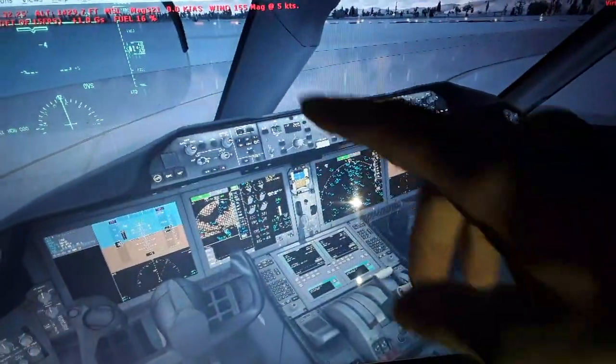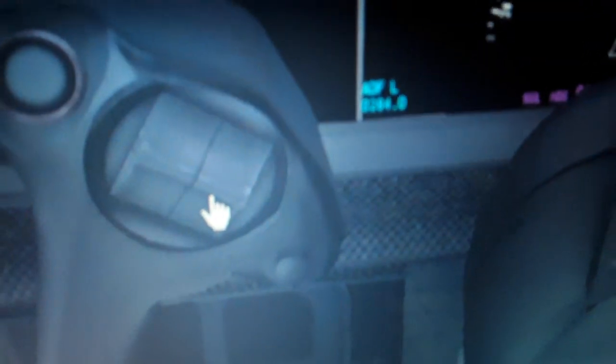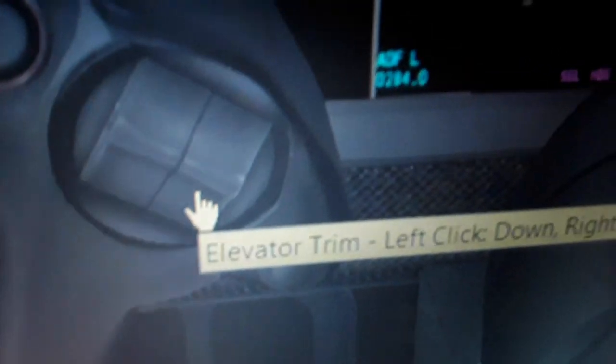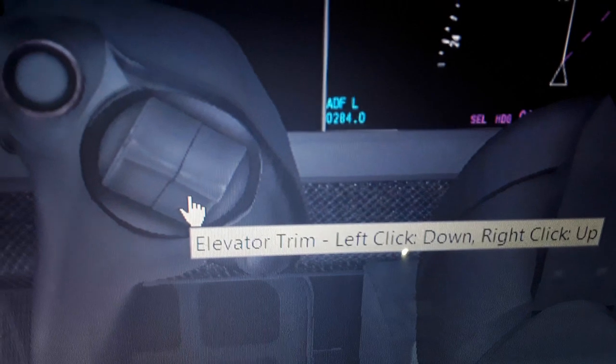So after you disconnect the horizontal trim function, you have only the manual trim over here again, only the manual trim channel. You lose the auto trim function, so you can see again the elevator trim, so you trim like this manually after that.